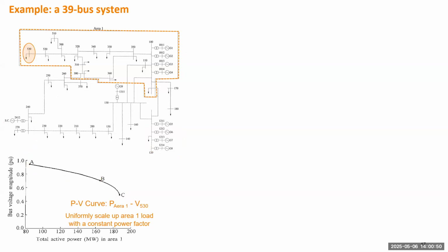Then we can draw this PV curve. So we only have the top branch above the critical point, because we cannot solve power flow when the load reaches the higher condition. So we only have this part from A to C. We color them differently.